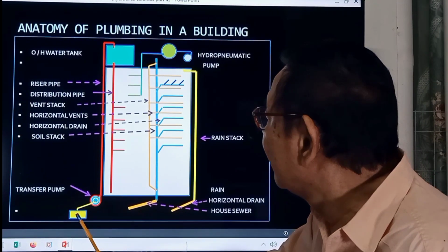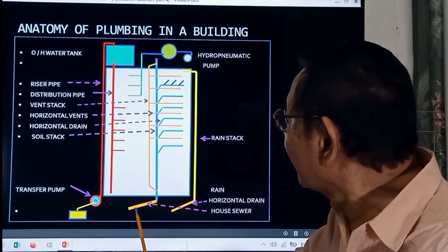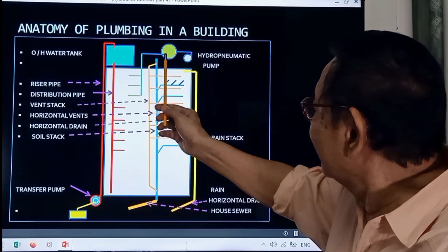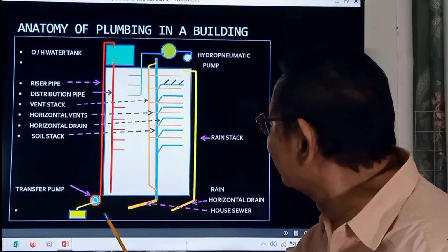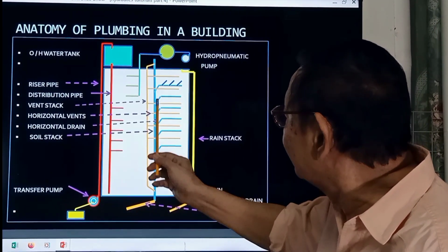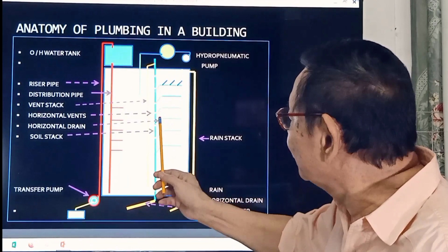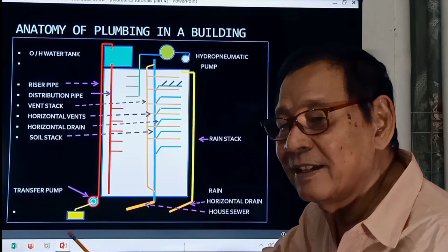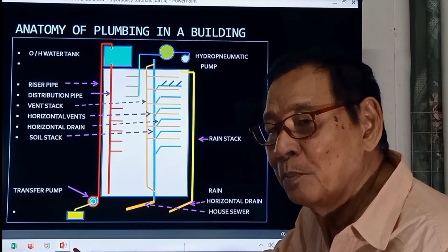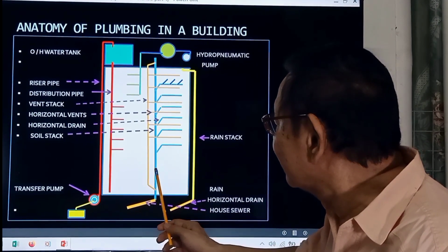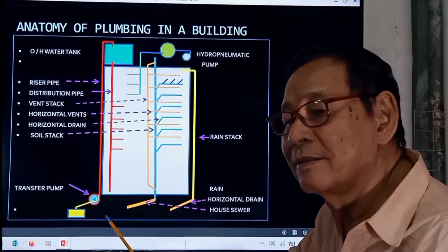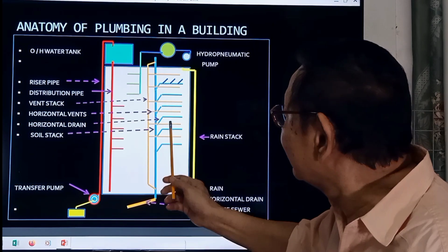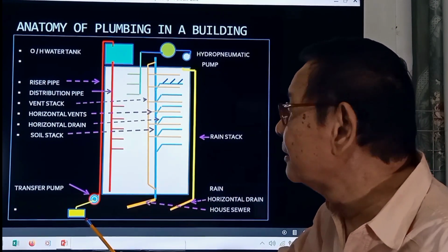Okay. The same thing also in the sewer stack, that each drain system are discharging to the sewer stack. If it is not designed, maybe the sewer stack is not appropriate or not being sized correctly depending upon the discharge of the horizontal drain.